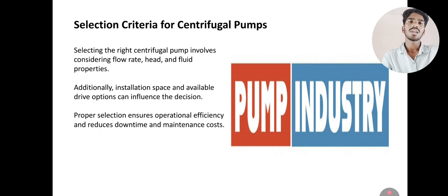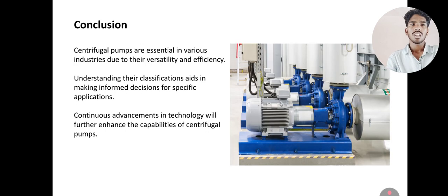And the selection criteria for centrifugal pumps. Selecting the right centrifugal pump involves considering the flow rate, head and fluid properties. Additionally, installation space and available drive options can influence the decision, and proper selection ensures operational efficiency and reduces downtime and maintenance cost.